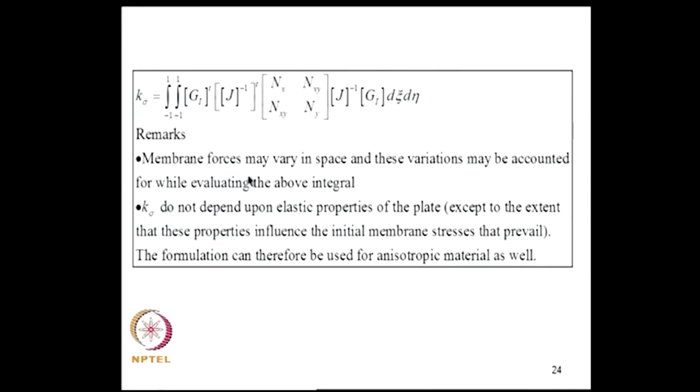Now, if membrane forces are taken to vary in space within an element, that can be incorporated here in evaluating this. But then while choosing the order of integration, you should have an idea what is the order of variation of this Nx, Ny and Nxy. Typically, you can assume linear or quadratic variation and then decide upon the order of integration.